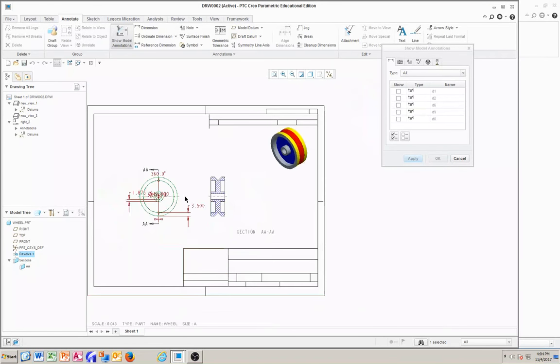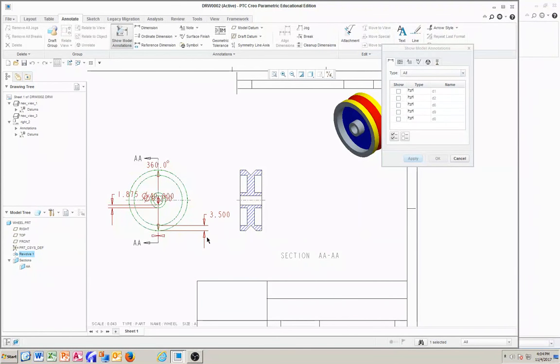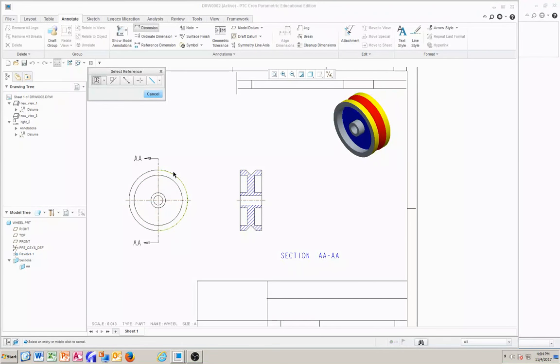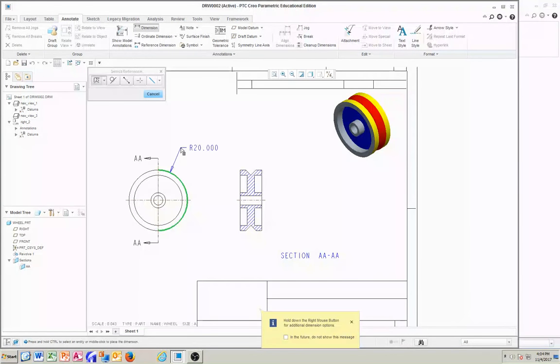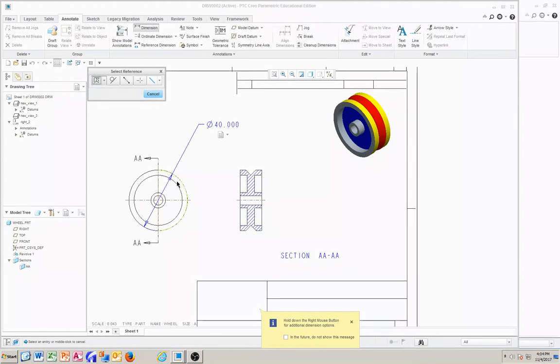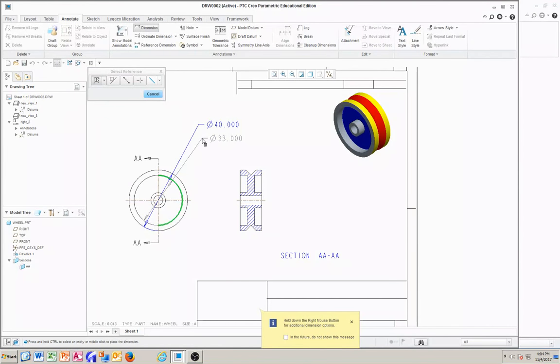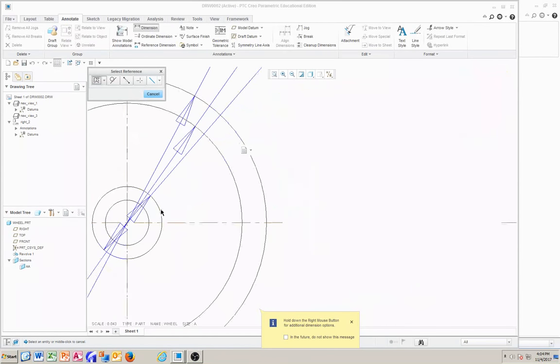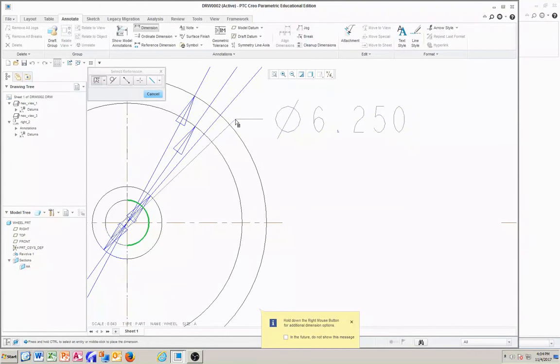If I do that, it says you have the thickness between this wheel and this circle, and this is 3.5, but this is too much. I think I'm going to just do the manual dimensioning. So I'm going to say this is, oops, two clicks for diameter. Diameter 12, and this one 12 diameter, and then another 12 diameter, and another 12 diameter, see that?